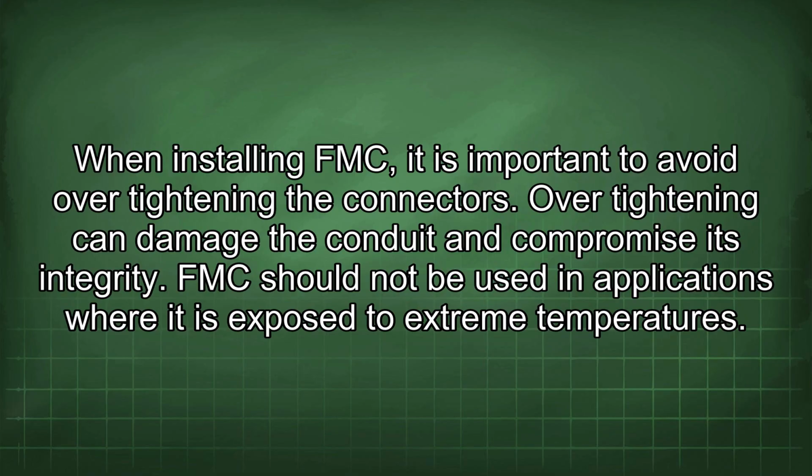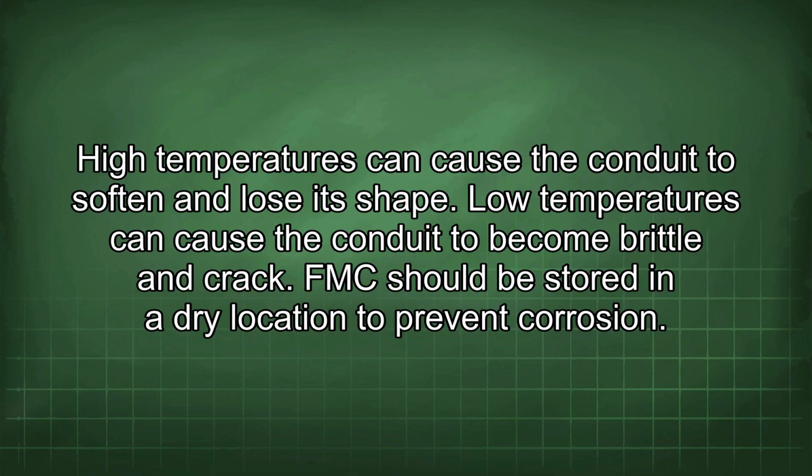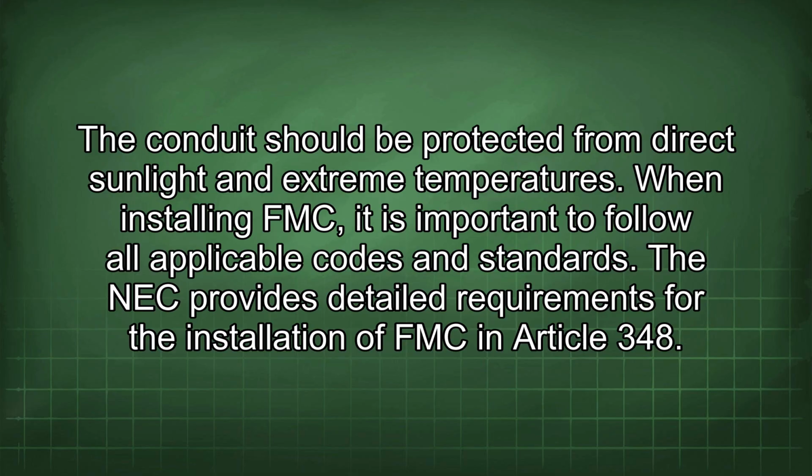FMC should not be used in applications where it is exposed to extreme temperatures. High temperatures can cause the conduit to soften and lose its shape. Low temperatures can cause the conduit to become brittle and crack. FMC should be stored in a dry location to prevent corrosion. The conduit should be protected from direct sunlight and extreme temperatures.